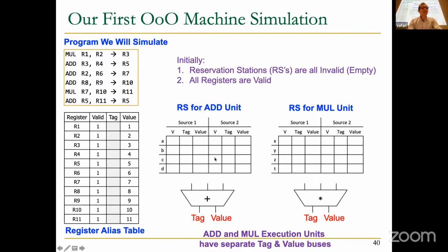When an instruction starts executing in the adder unit, we take the 2 values that had better be ready for execution. Then we take the destination tag that we're going to produce. For example, if this instruction over here starts executing, we're going to broadcast tag A, saying that this is the value the instruction at reservation station entry A is going to produce. Anybody who's waiting for A is going to capture that value. Does that make sense? We're going to rename these registers to reservation station entries that are holding the instructions that are going to produce the values of those registers. That's the idea. Very similar to the reorder buffer, except this is the reservation station.